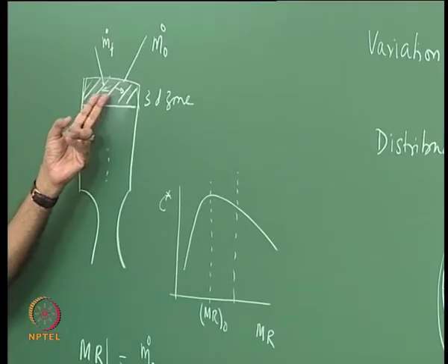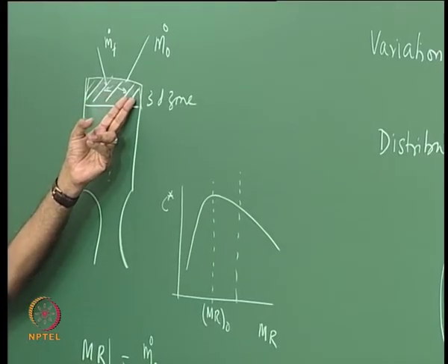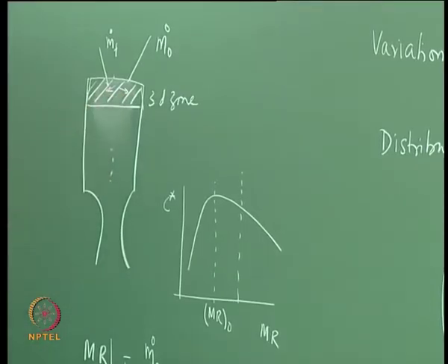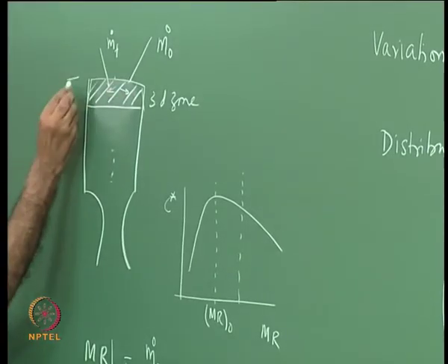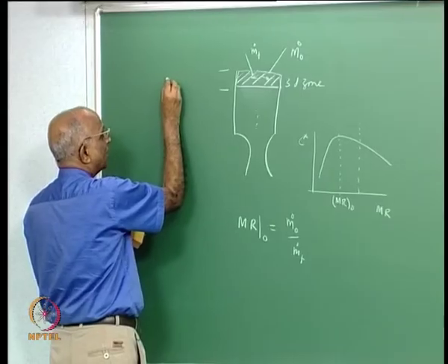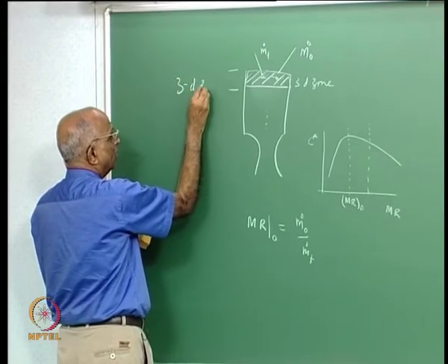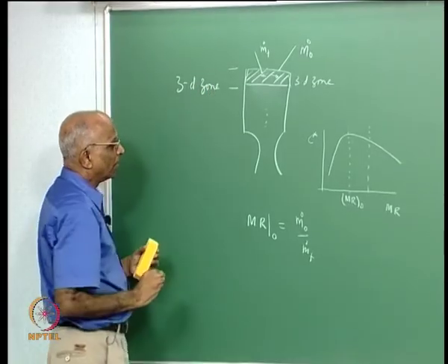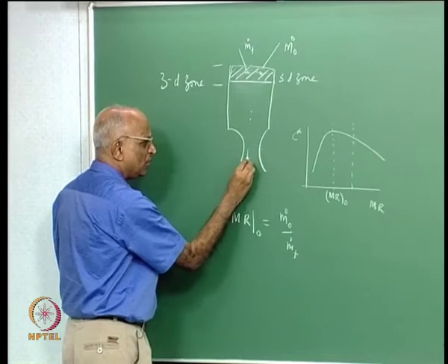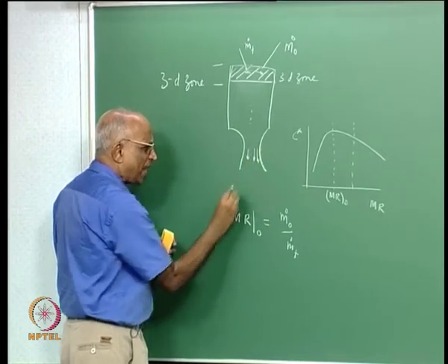Droplets are travelling like this, maybe some vaporization is taking place here, and therefore to quantify this zone is a little difficult. Therefore, I say immediately downstream of injection, because I inject in different directions, I have a 3-dimensional zone. But I also know when I come to the throat the flow is sort of normal at the throat, the flow is axial at the throat, right.